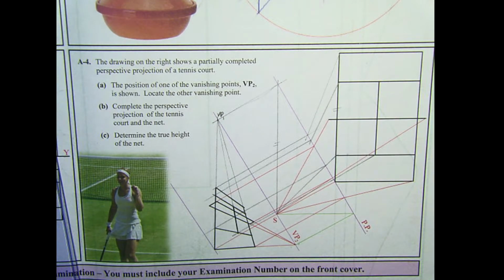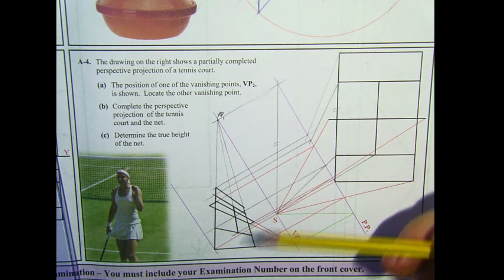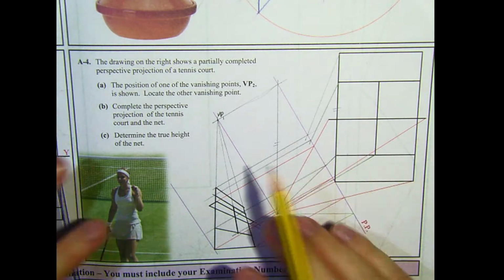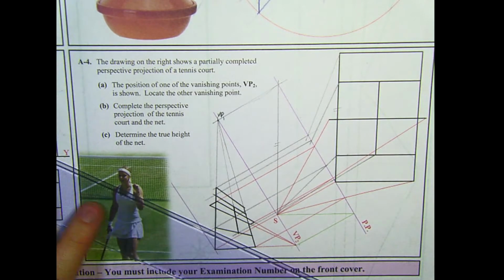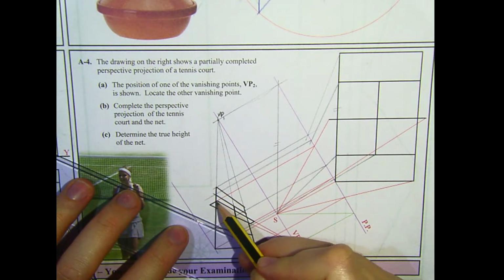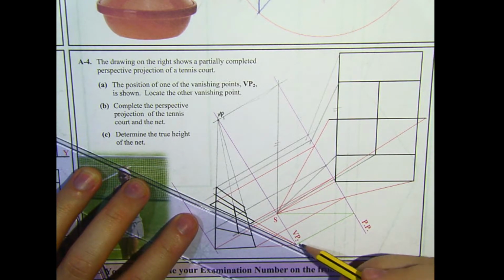The final part of this question is to determine the true height of the net. So the only way you can see the true height of something is if it's on the picture plane. So we need to project stuff. We can either project it down here onto the picture plane, which is a bit unnecessary at the moment. So what we can do is, if it's on the ground line, then we can also see the true height of it. This is the net, so I'm going to project from the vanishing point 2 along the net,